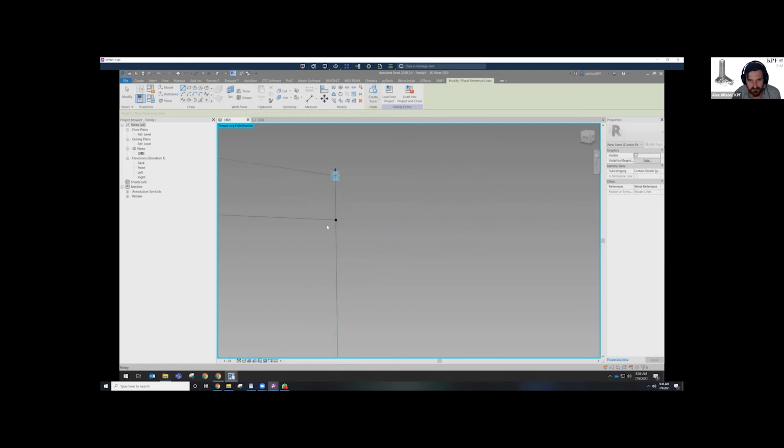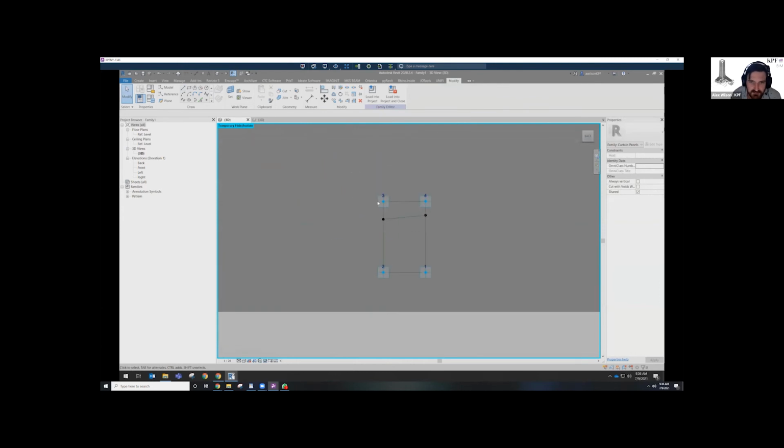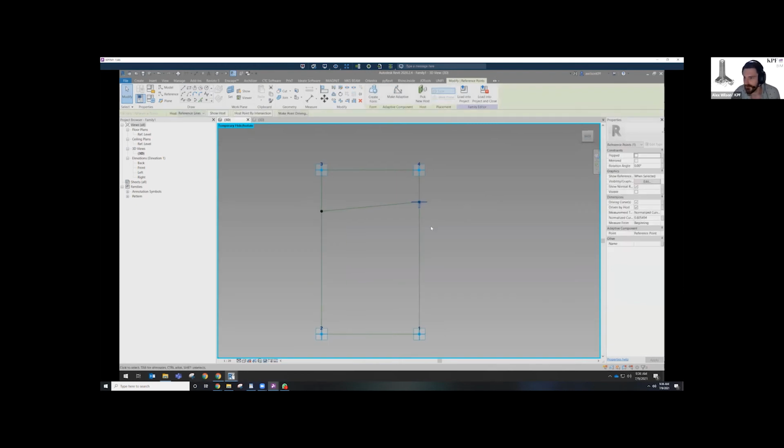And I can connect the points like this. Now at the moment, you can see that my transom is, let's just say, a unique design. So what I need to do is make it flat. I've selected this point, and now we're going to talk about length along curve.